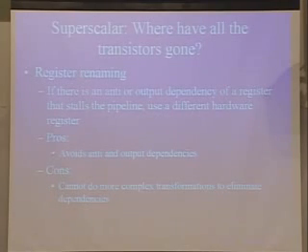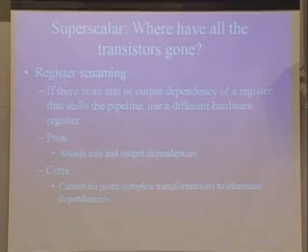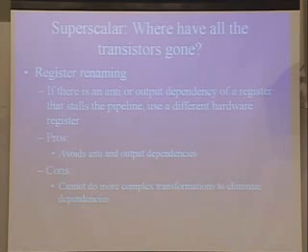So assume I have a register in there, and I am waiting to write it. I'm waiting to read that, and somebody else wants to write to the same register. And right now, normally what happens is, oops, there's an interdependence, I just have to wait. But modern hardware has a difference between virtual registers and physical registers. They have many more physical registers.